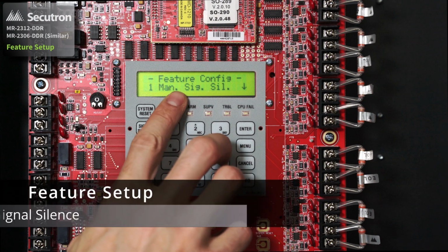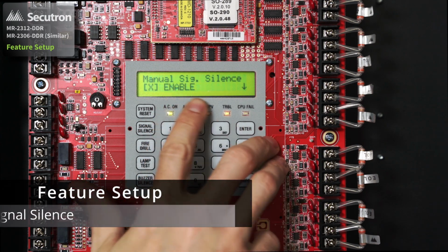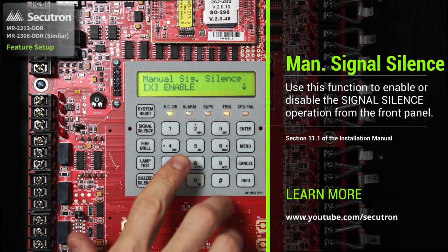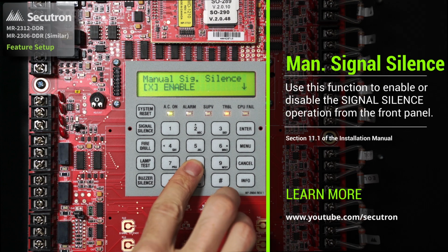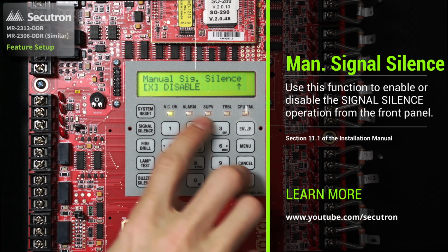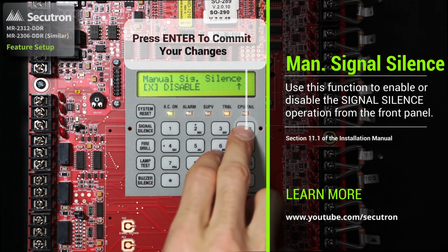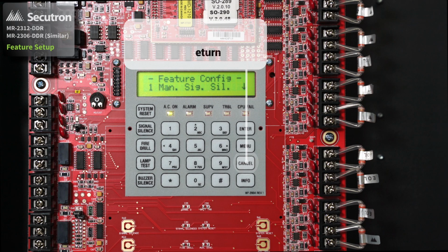One of the first features that comes up is manual signal silence. If we select Enter, we can go into whether we want to configure it. By default, it has been selected as enabled. If we'd like to set it up as disabled, we'd hit the down cursor and then hit the left or right cursor to place the X. Once the X is hit, we can then go back, and now our manual signal silence will have been disabled.